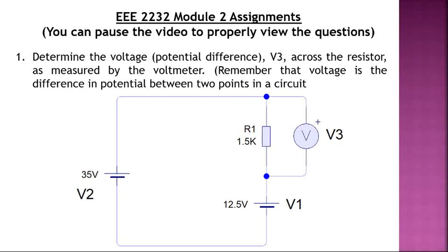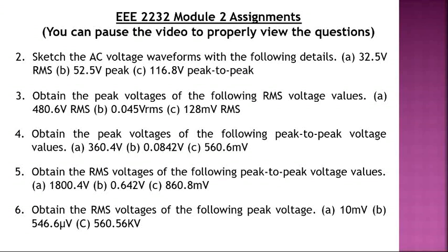So we've considered the ideal scenario, where you use calculated values if there is no unexplained drop in voltage, and when you use measured values, where there are drops due to the internal resistance of the voltage source itself, which is not shown in the circuit. The voltage source itself is dropping for some reason due to its lack of capability to produce its rated voltage. It's supposed to produce 1.5 volts, but for some reason it's supplying 1.36 volts, something like that. So there are little discrepancies between our measured value and calculated value, and we treated both cases.